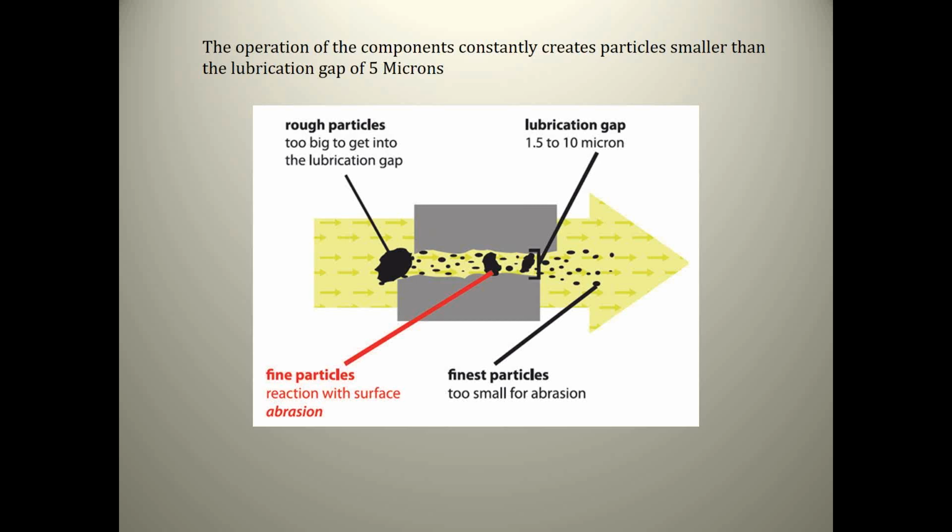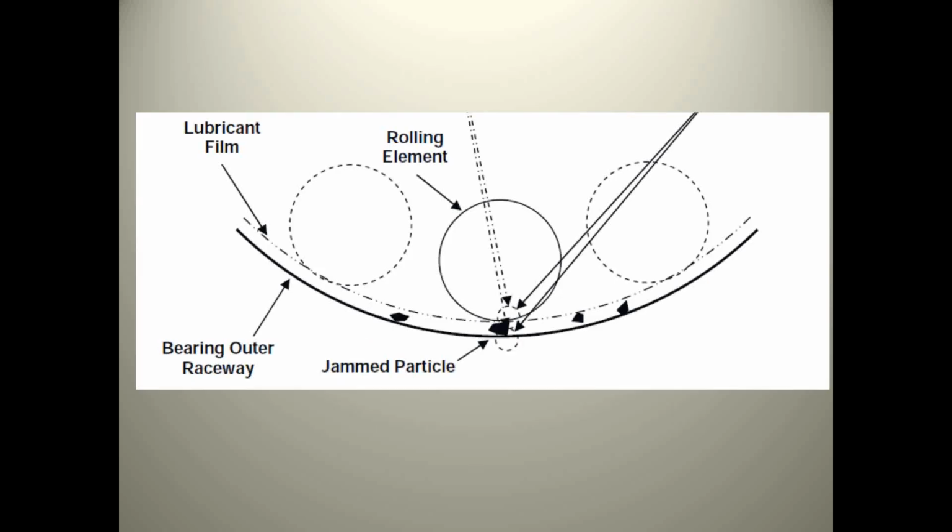And in the process of grinding up those particles, you're actually wearing out your components. At some point, some of the particles will be iron off your components. In one of my training classes, I have some slides where it shows the ISO codes on the oil getting dirtier and dirtier, and then all of a sudden it shows the iron number and the tin number going up on the lab report. When you see that number increasing, what that means is you're wearing out the components. Those iron numbers are increasing in your lab analysis sample, and it's due to wearing out the component.